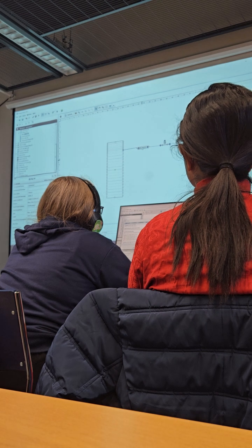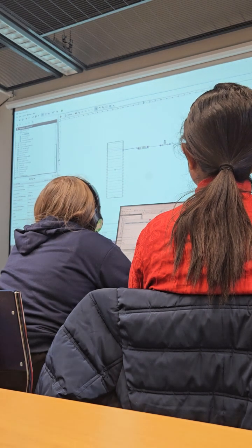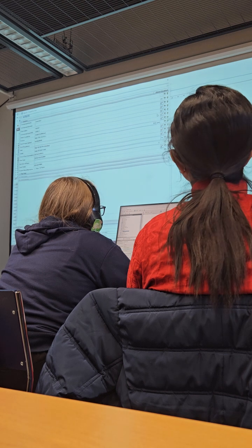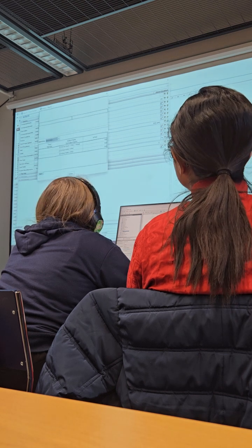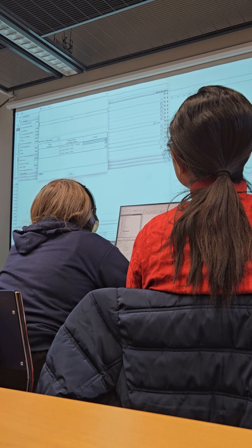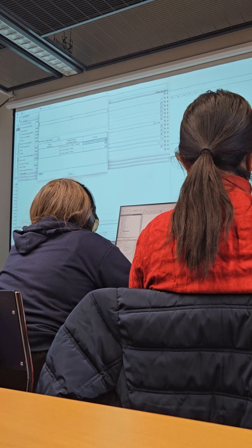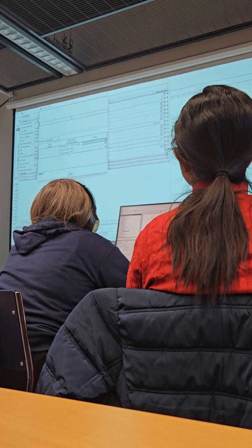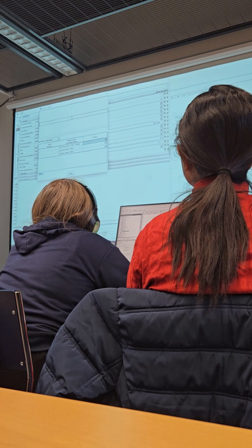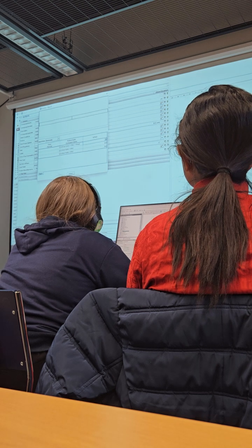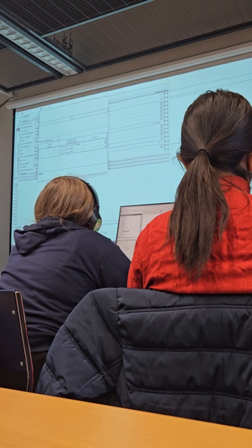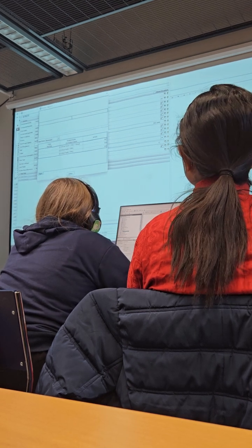I have to give here some loss factor value, which is the same place as we did the friction. We didn't put here the K factor, which is related to this abrupt area change. You could check those from the literature, but I could put here any value, maybe 0.1, so that it makes the code happy again.